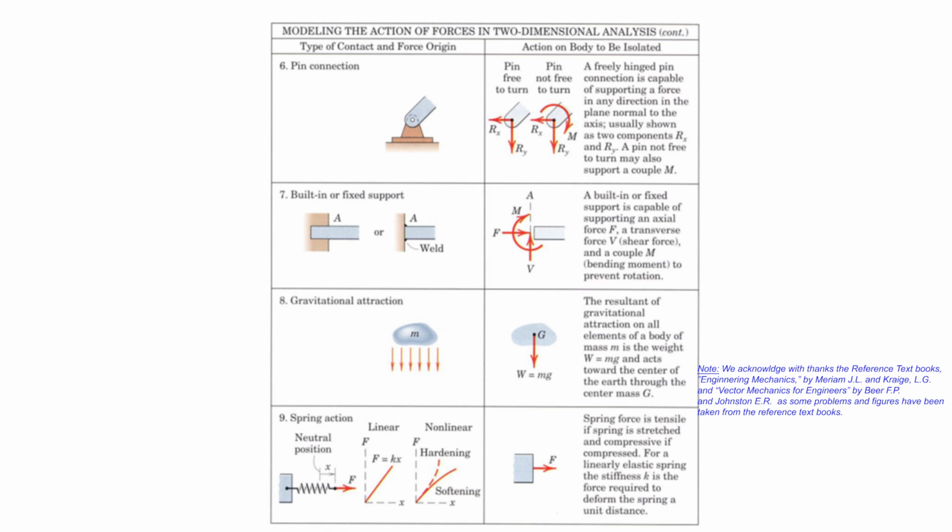When you solve the equilibrium equations, if you put F in the wrong direction, F will turn out to be negative at the time of the solution. If you know it and put it properly, you will get a positive answer. But if you don't, it's still okay.